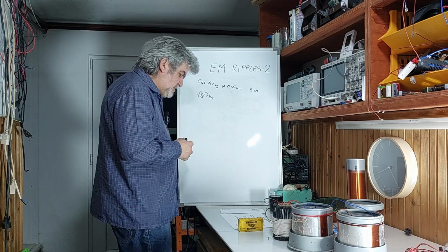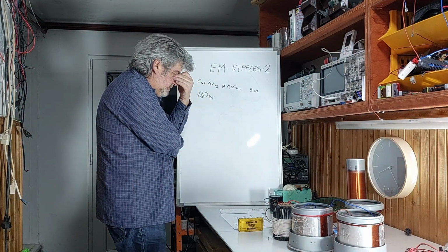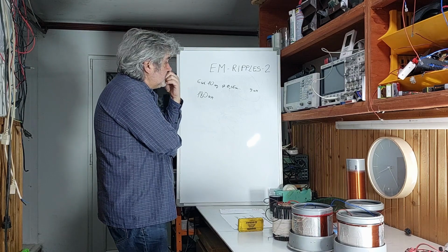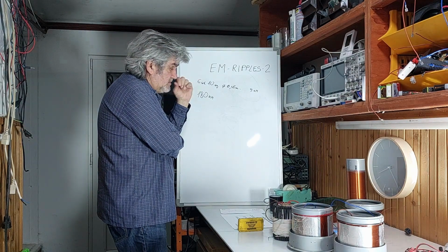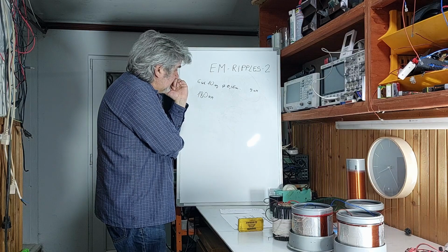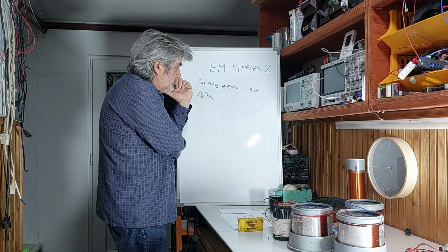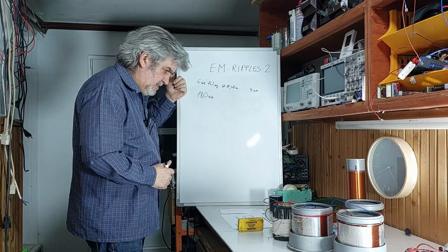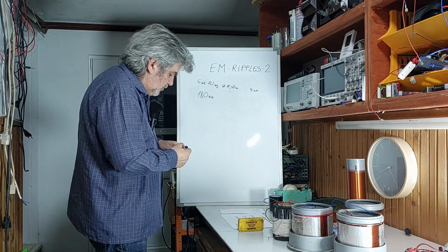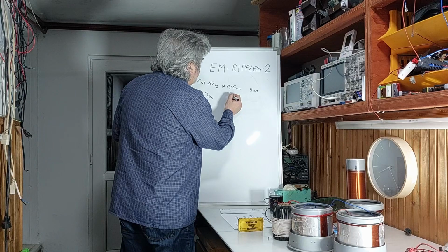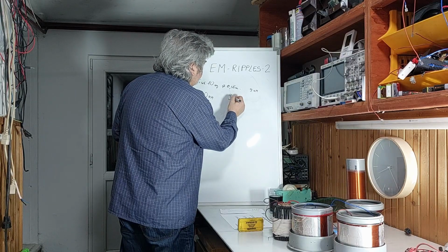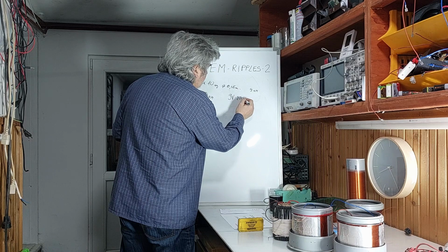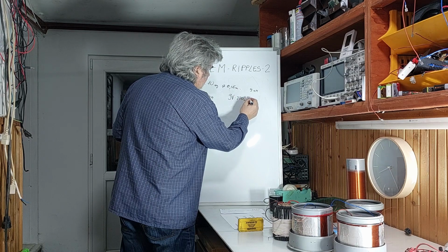Because I used a reed switch to run it, so I didn't use a commutator like his, I used a reed switch for switching. And I used a 9-volt battery, 200 milliampere hours.